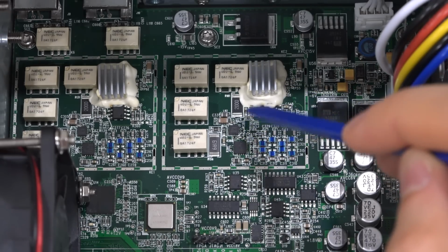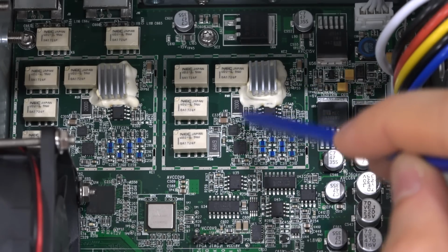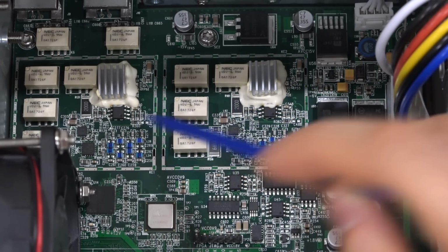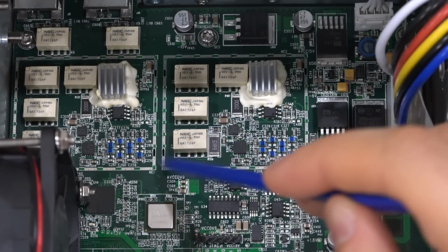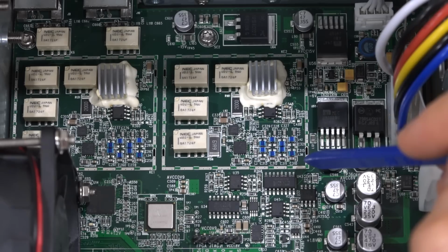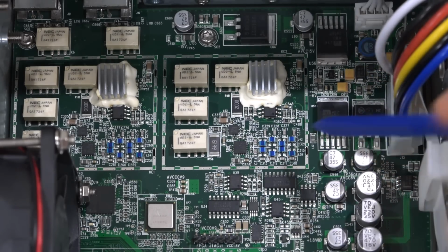Now as soon as you go single-ended here and you put 40 volts peak to peak output here, I would like to test to see how much isolation you have to the other output, because now you have a huge signal here and there's no cage. And you can see the footprint for a cage is here, but it's not populated. Perhaps they have deemed that it was unnecessary in their testing, that the isolation was good enough even without the cage. Let me give you some more voltage regulators over here.